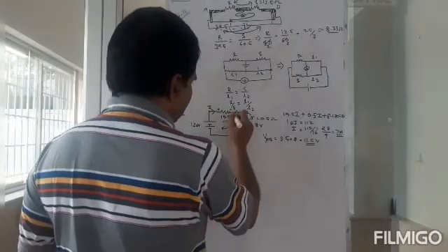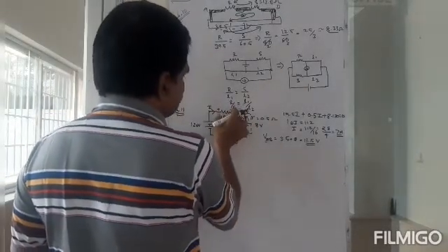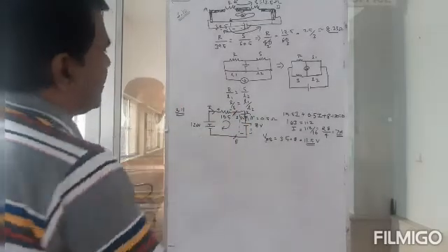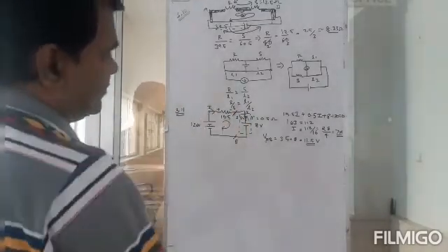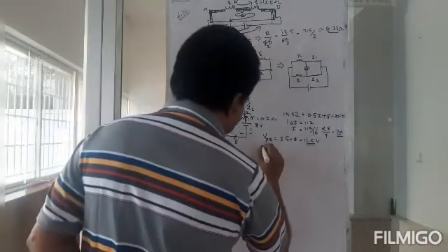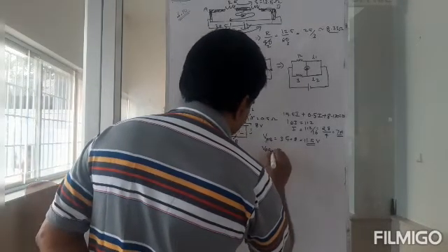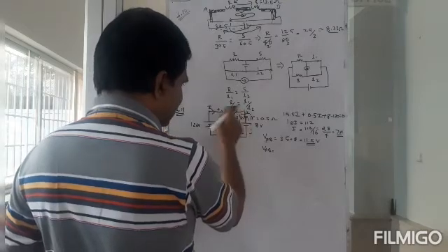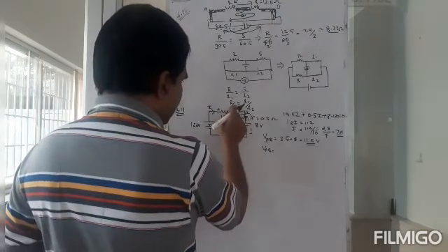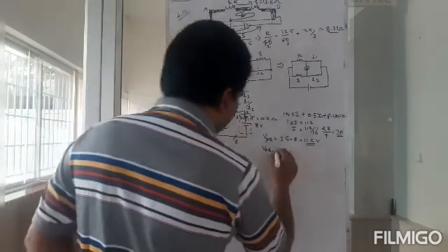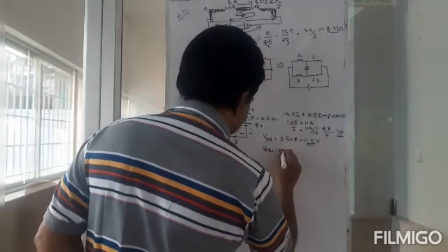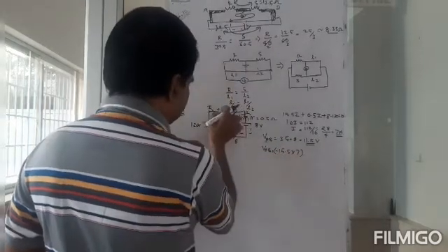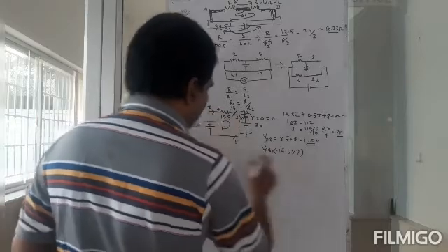VAB, right? Okay, let me take this. What is this voltage? It's going to be 15.5 into 7. Okay? So let's say, what is VAB? Another way of doing it. If we go this way, this is minus. I entered through the minus terminal, right? So minus 15.5 into 7. That is this voltage. And I am entering through the positive 120.